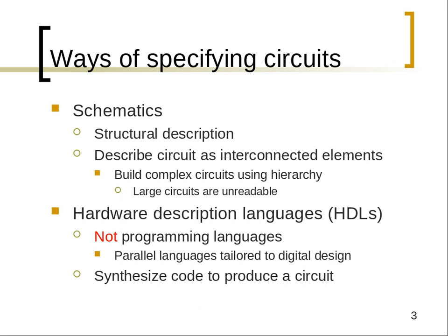You're not describing how it happens, you're describing what needs to occur. Then Verilog is going to run the simulation. This is very important to get, because if you try to think of it as a programming language, executing one step at a time, you're going to run into trouble and probably never get a hold of Verilog. It's Verilog's job to produce the simulator for your design.